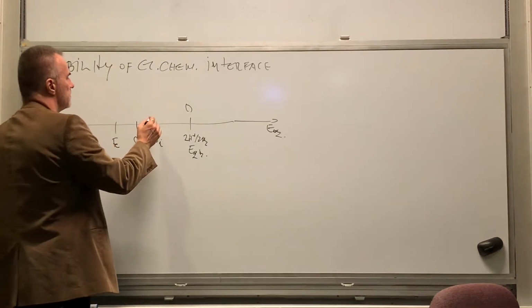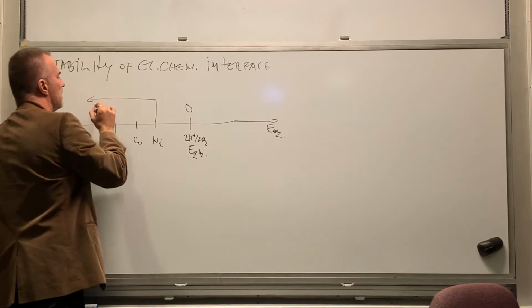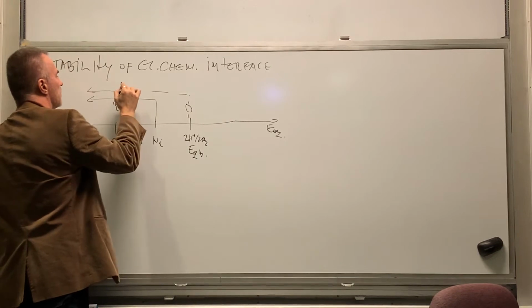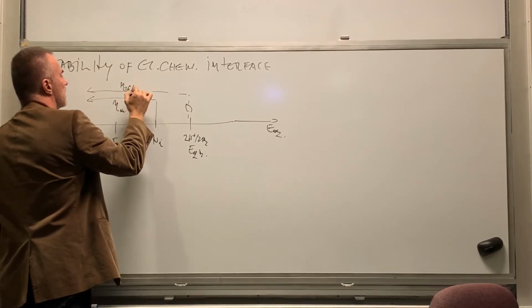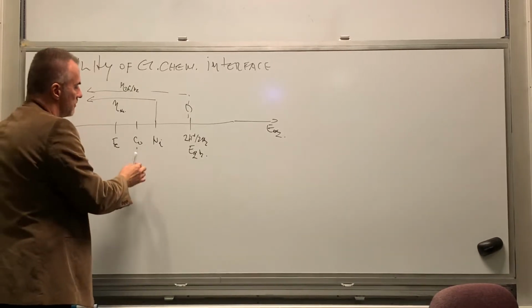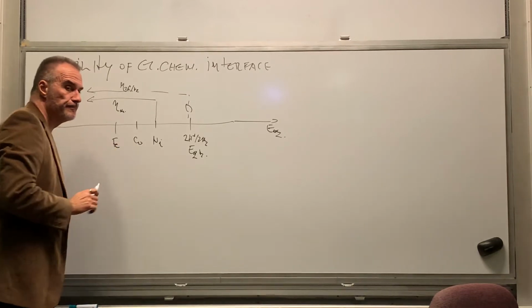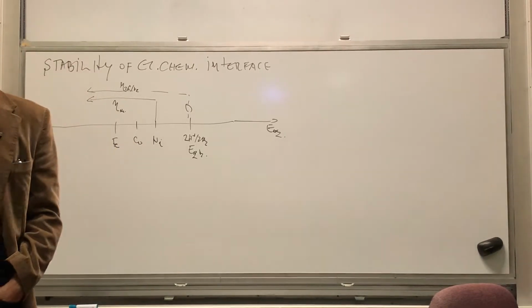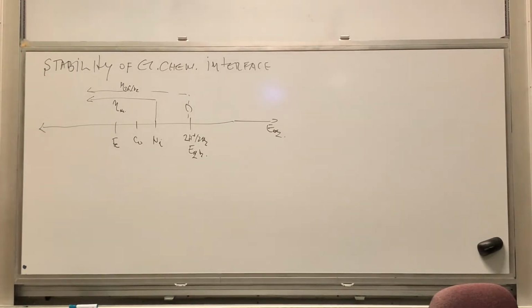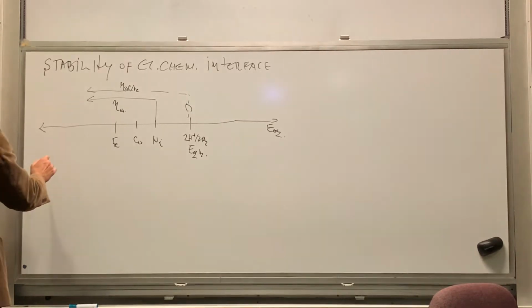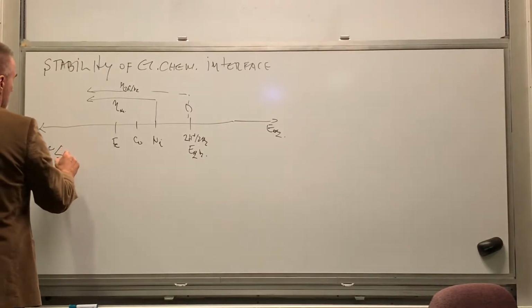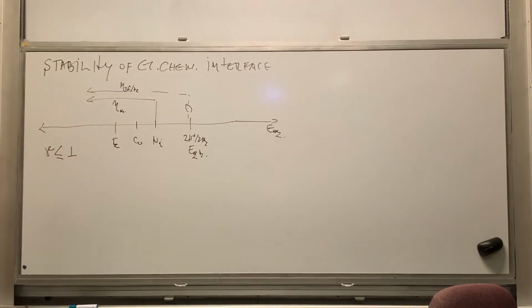What that really means is that if I'm trying to deposit nickel and applying some overpotential for nickel deposition, at the same time I'm applying overpotential for hydrogen reduction or the hydrogen evolution reaction, okay? And basically the same applies for cobalt, for iron, etc. So what that really in general means, as we discussed last time when we talked about specific metals, is that the efficiency of the current is generally less than 1.